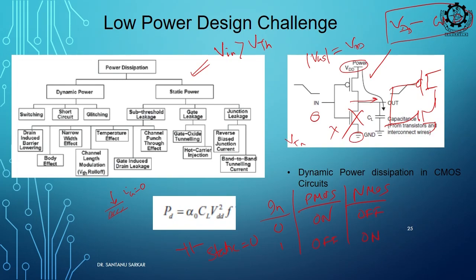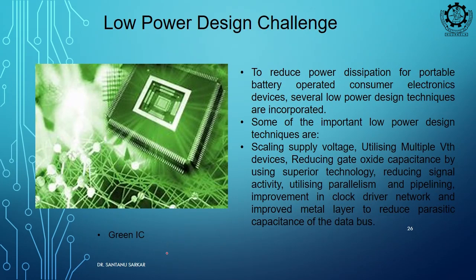Okay. So, in initial applications, if your frequency of operation is low, then it is very good, but as frequency started to increase, what will happen? I have a VTC like this. When it reaches the middle point, both of them will be above the VTH, right. When the input is at the extreme, one is on, another is off, but what will happen when the input is at the middle? So, this is called the short circuit current, right, both of them are on.